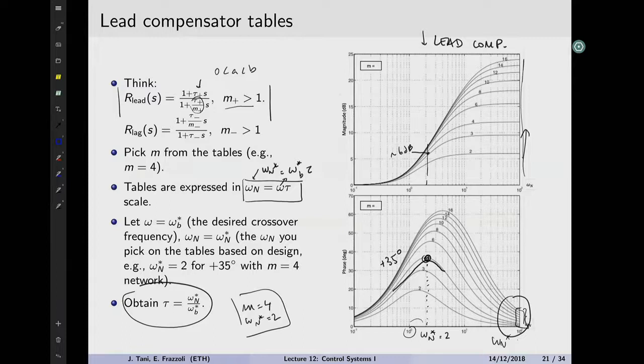And you flip over the equation and you get how much the magnitude of L needs to be to satisfy this constraint. You get that number in dBs. So it's like putting an obstacle at low frequency that is a constant, saying up to 6 hertz, you want the magnitude to be more than that. So you have to start the design from the S, but then you flip it over to the L, as we saw in those slides on reverting the specifications to the open loop terms.